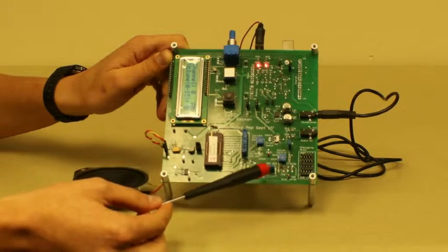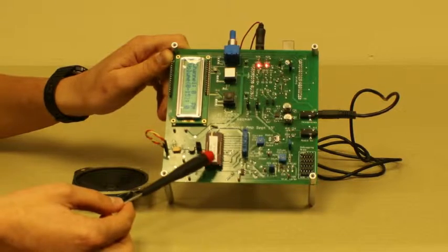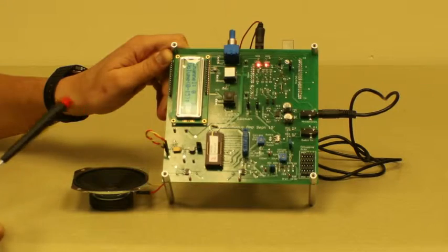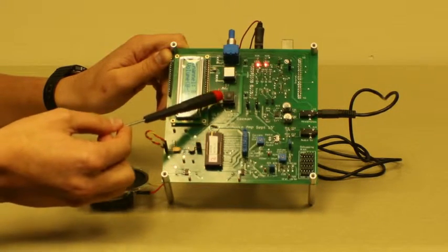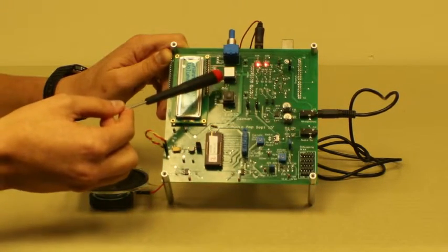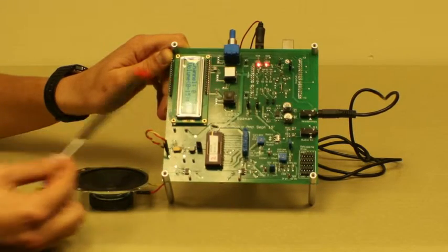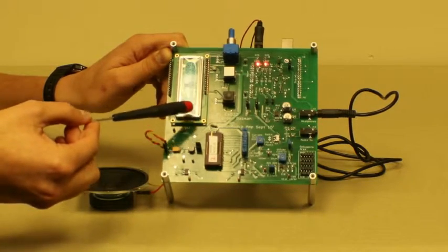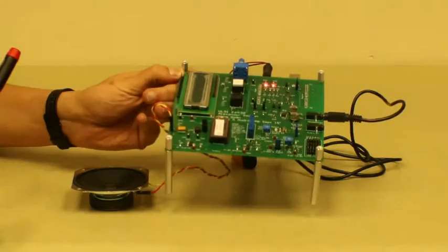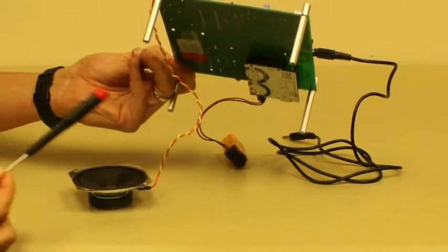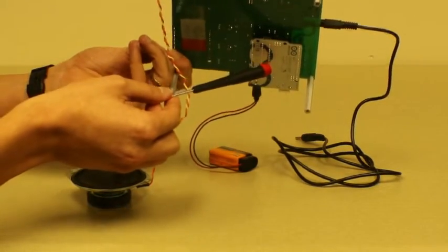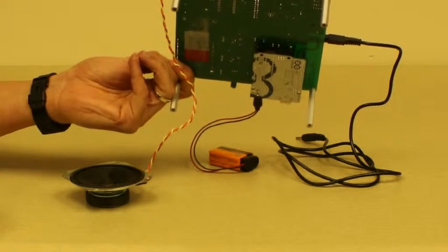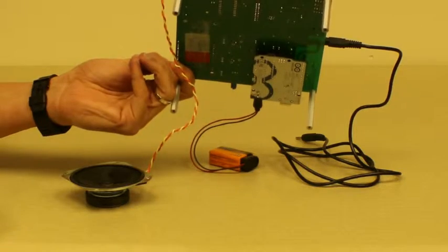Then the audio propagates to our audio amplifier, and then through a filter and directly to an 8 ohm speaker. The radio can also be controlled through two knobs over here, one seeking channel up and the other seeking channel down. We have a volume control and an LCD which shows the channel and the volume. The board is powered through the 5-volt Arduino board at the bottom, which also controls the FM radio receiver through the I2C protocol.